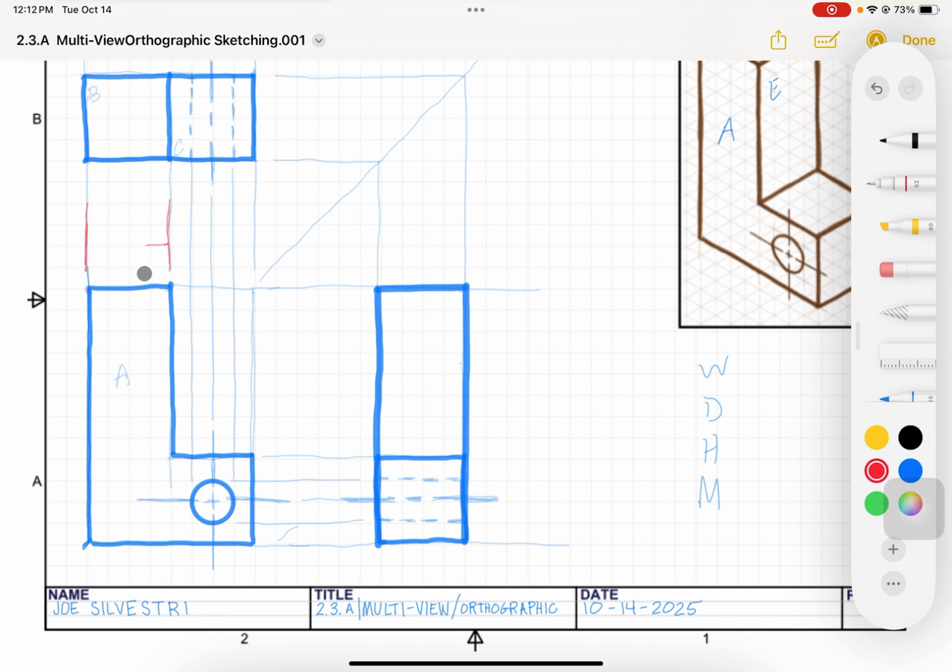and I want to put my dimension line in here. Now remember from our notes, a dimension line is a line with a gap in it somewhere. It could be the middle, doesn't have to be. And it has real small, tiny, filled in arrowheads like that. Okay, so this is where the 2 comes in. So far I've got a 1 block gap, and then the dimension line is 2 blocks up from the outermost edge. And then last but not least, I want to have the extension line extend 1 block past the arrowhead. So that's going to be a 1, 2, 1.